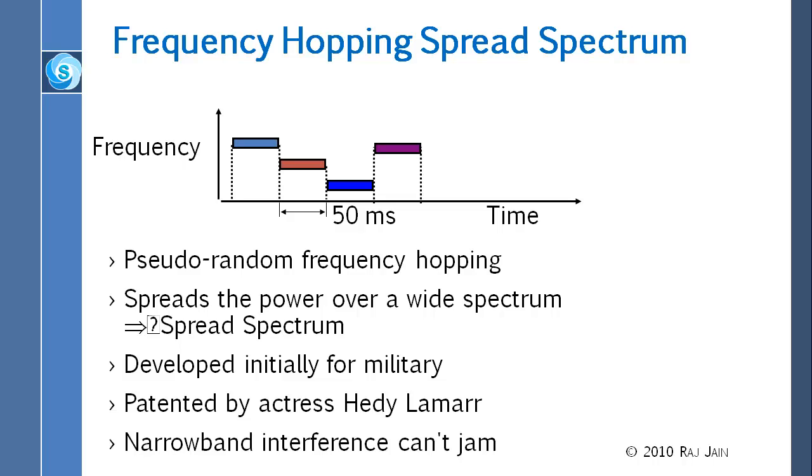Right. So that's a very good point: if my clock starts in the middle of somebody else's clock, I would get half at this frequency and half at the other frequency, and I'll be very confused. But what happens is, before we start communicating, we send a signal which basically synchronizes the clock. So we send a training signal which tells you exactly where my bits begin. That signal is well known, 0, 1, 1, 0 or something, some well known sequence, and until you get exactly that sequence, 1, 0, 1, 0, you know that you are not synchronized.